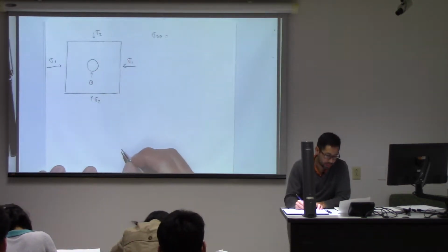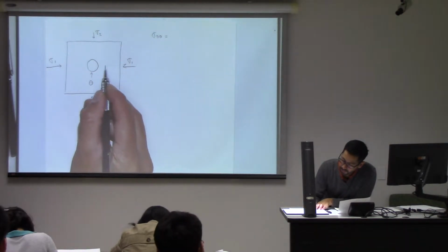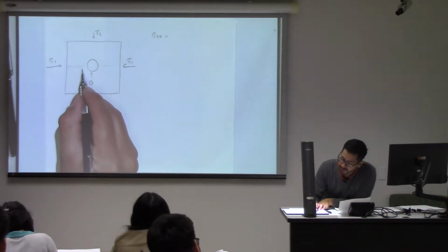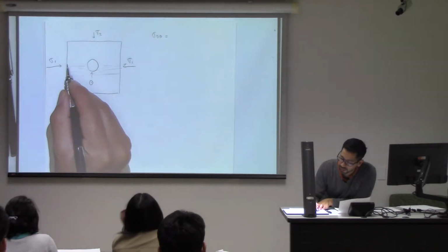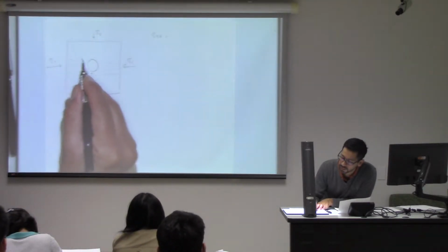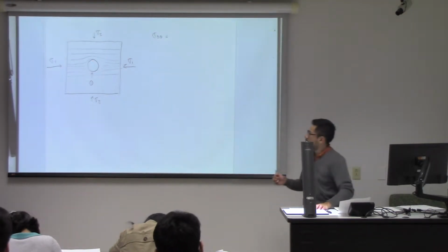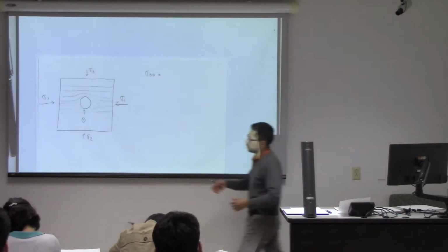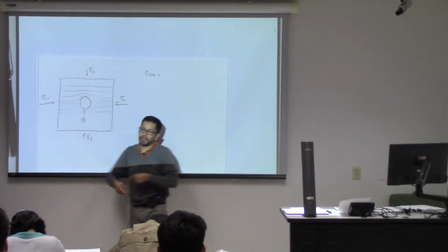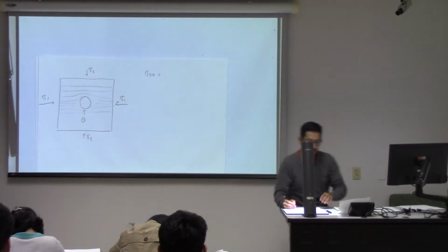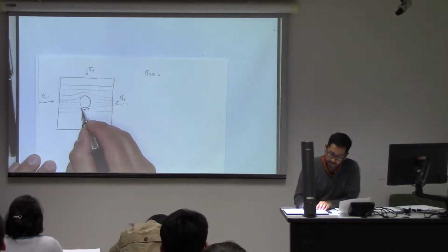In that point, you have a lot of accumulation of compressive stress, because your compressive stresses are deviating in order to go around the wellbore. Everything that was going through the wellbore before now has to go through the sides, and because of that, you're going to have a lot of compression in this location.